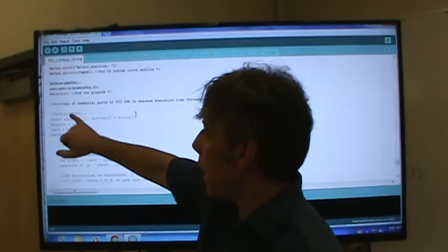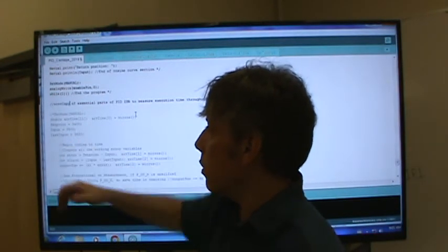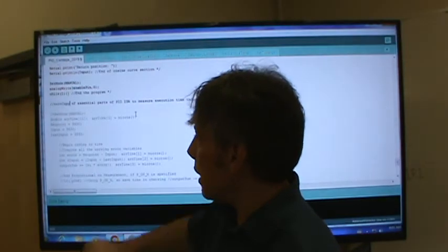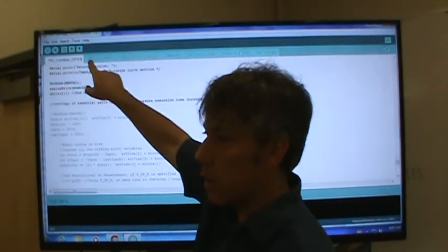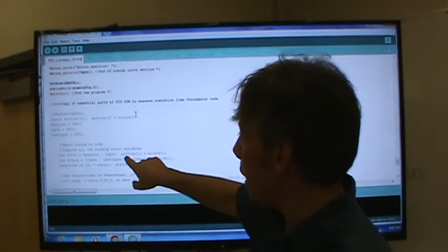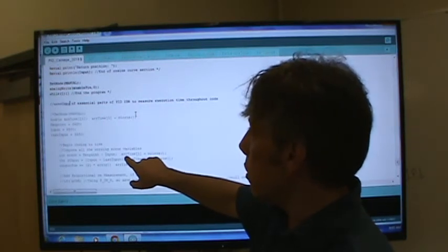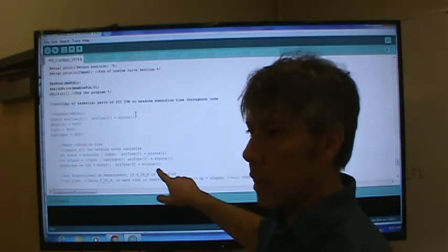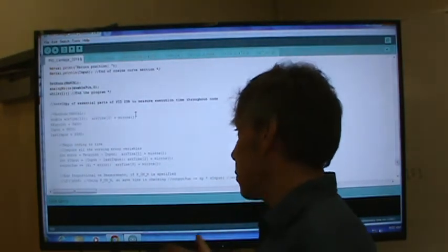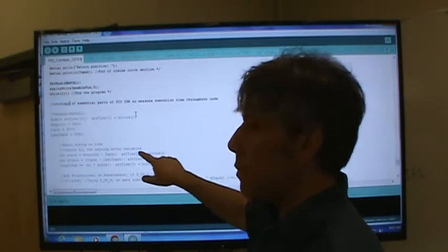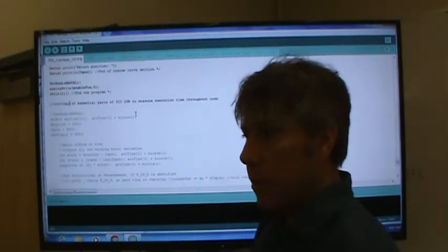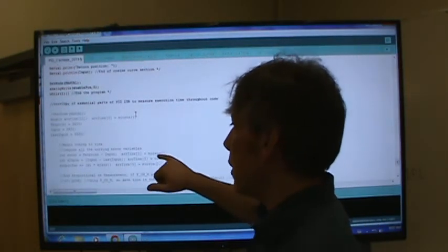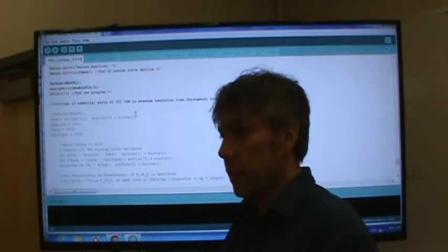First thing I did was I moved the carriage to about the center point, and then I began the calculations that would normally occur over here. What you'll notice is that I made an array where I could just note the time in microseconds after each instruction has been completed. Now, there's a problem here. Noting the time takes time also, right? So the microsecond clock is advancing while I'm basically jotting down how long the last command took. But at least it gives me an idea where the longest section of the code is located.